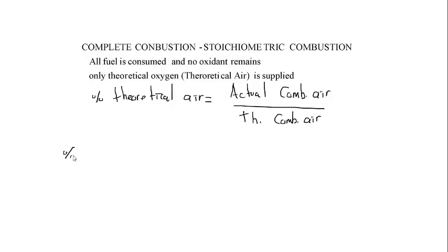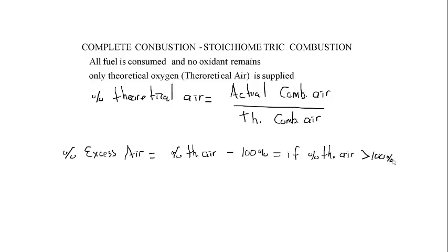Percent excess air is just your percent theoretical air minus 100%. And that's if your percent theoretical air is greater than 100%. So that means I have more air mixing with the reactant than is necessary for complete combustion.